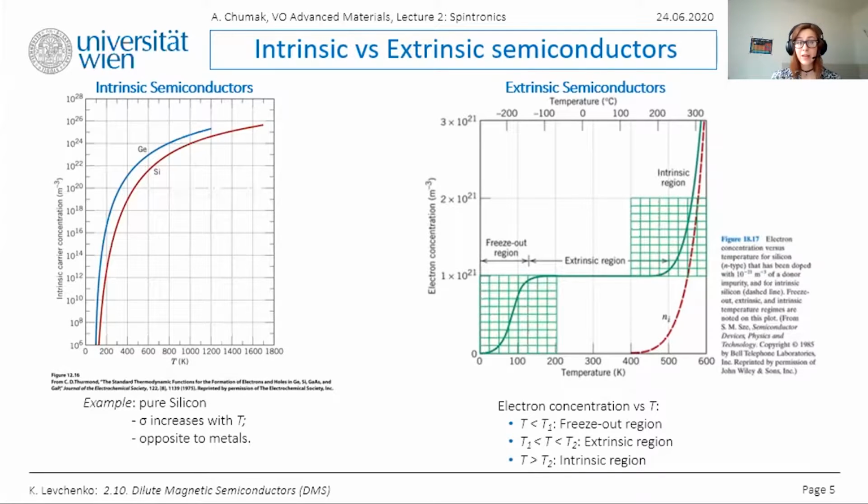Conductivity of a material is determined by two factors: the concentration of free carriers available to conduct the current, and their mobility, or the freedom to move. In a semiconductor, both mobility and carrier concentration are temperature dependent. Thus, it's important to view the conductivity as a function of temperature.